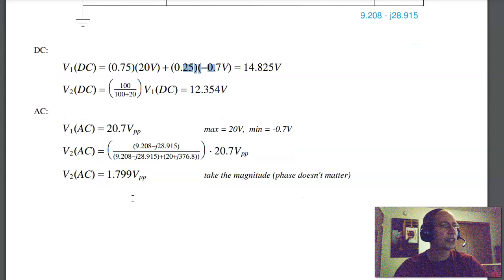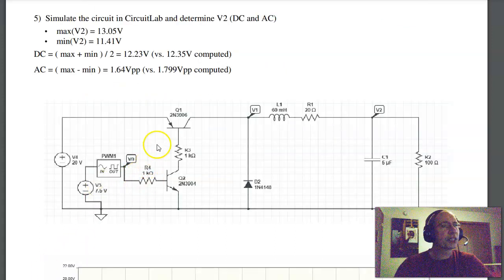And in Circuit Lab I can check. If I build the circuit in Circuit Lab, this is actually that switch. The PNP transistors go to power, NPNs go to ground. If R3 is to ground, this diode is turned on, Q1 saturates, and V1 is 20 minus 0.2, 19.8 volts. If Q2 is turned off, then there's no current flow and the switch is open.